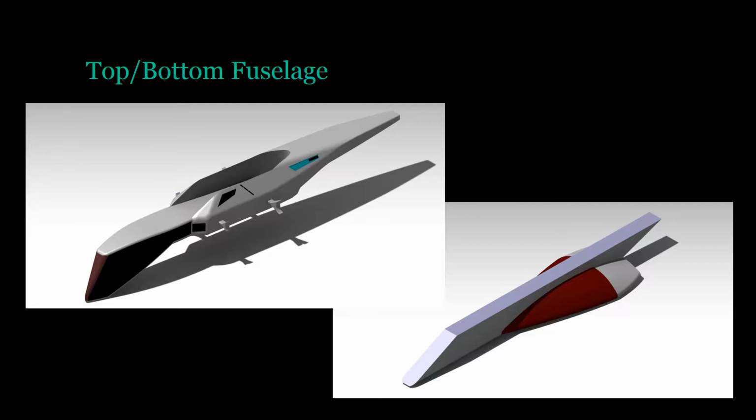I initially started using GSD, but realized that that would not work fairly quickly. So instead, I switched to sketch tracer and part design. I started with 2 sketches, one at the top and one at the bottom. I then used solid combine to make the first initial design. Once that was done, I started adding what I call just GSD touch-up designs, which is mostly all the side work. After that, it was almost completely done, and all I did was add color and stickers.